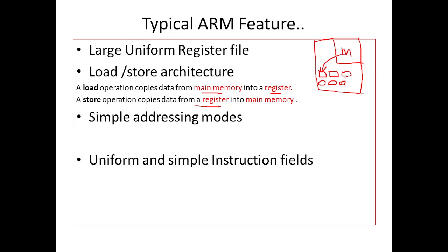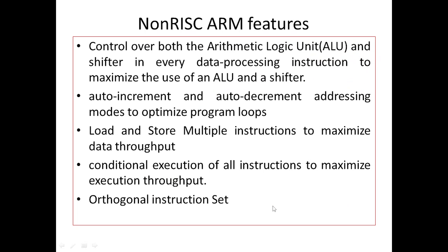So it is a store operation, and that is a load operation. Try to understand the meaning of these things, because when we deal with the memory, the number of cycles is different, compared to when we deal with the registers. That's why this load and store architecture is very famous in ARM. Simple addressing mode, uniform and simple instruction fields.